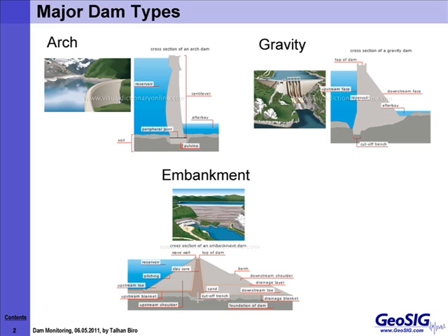And then comes the gravity dams. From the name one can understand that they are staying in place by the help of their own weight. They are relatively larger structures when compared to arch dams. They just carry on the pressure of the water that is retained by their own weight and the triangular shape of the body. And comes the embankment dams.